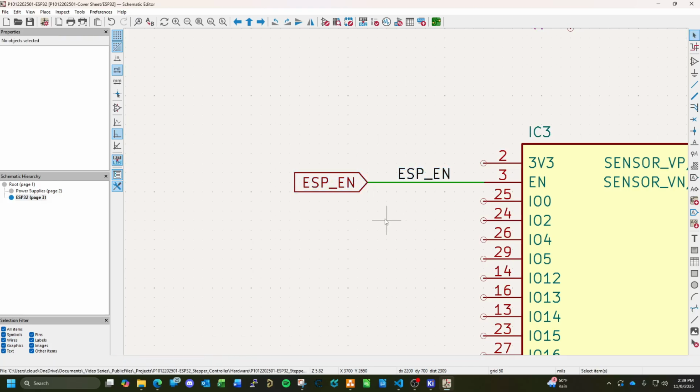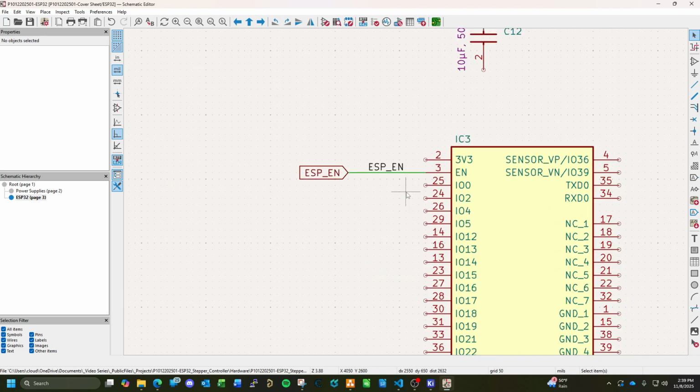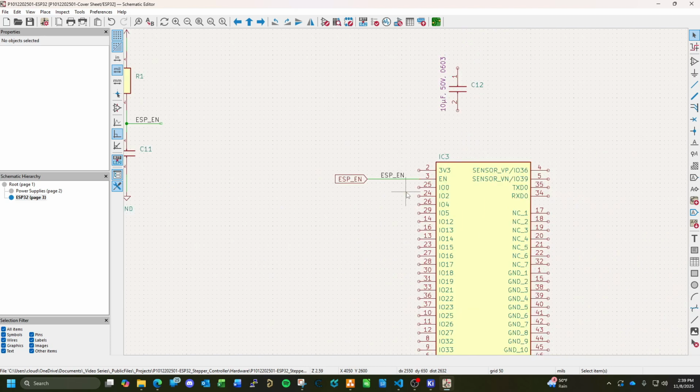So typically, what ports do is allow you to connect to a pin or a trace or a line on a completely different sheet than the one you're working on. As long as I put another port that matches this name on another sheet, they'll be electrically connected.